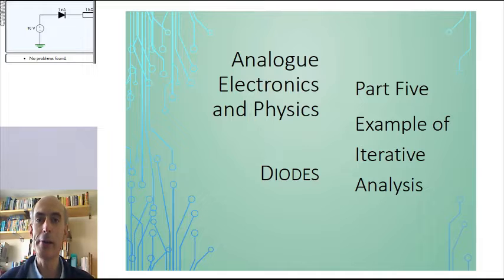We then compare that calculation with what the Shockley equation would predict. Given the results of that comparison, we can then make a better guess about the voltage across or the current through the diode. Repeating this process over and over again gets us to a very good approximation of the actual voltage and current of that diode.